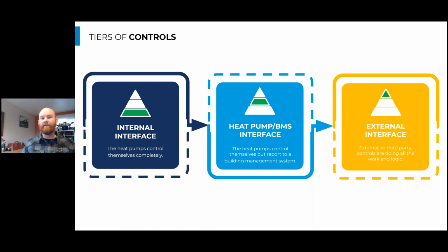So if you have a backup system, it's really critical and important, I would say, that you tie that system in or have some kind of control logic to notify the building maintenance personnel or the operators or the construction team that the backup is running, so they can be proactive on addressing what the problem is with the heat pump and making sure that they get it up and running to reduce that cost associated with our energy use.